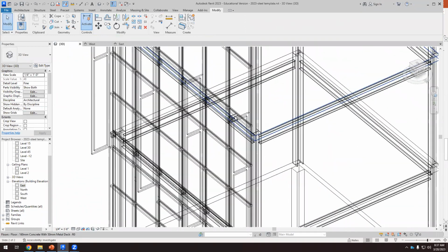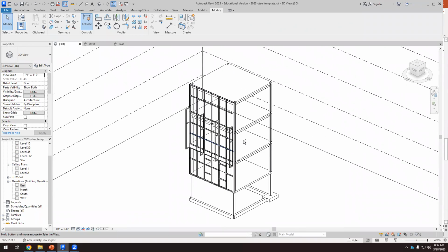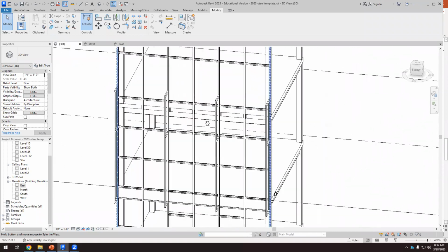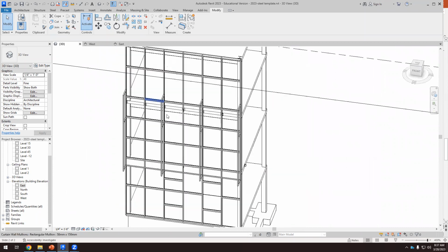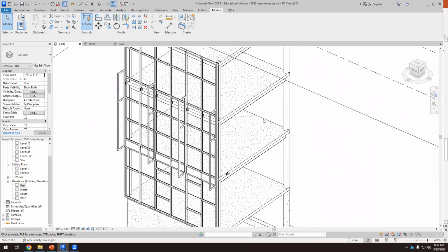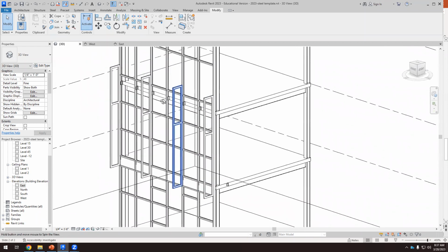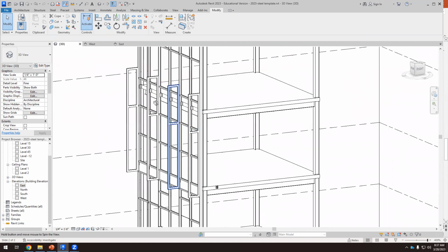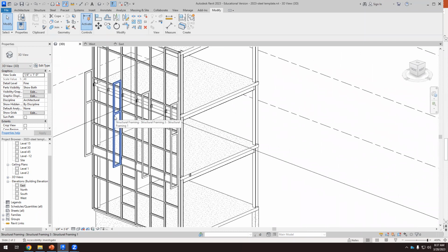Okay. So probably it's better first creating the structure that connects the double skin, and then we will create the mass adapting this to the structure. Okay, so I think that's clearer. Here we have the double skin. Here I have created that structure, and then I'm going to match the mass to that structure that I created. So I'm going to do the same thing I did last time. Now I have the family. So when I'm done with the mass, I will insert the family.